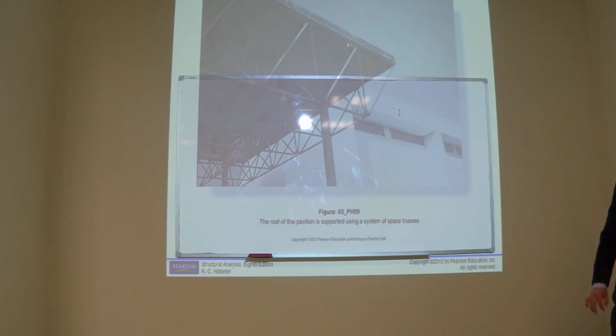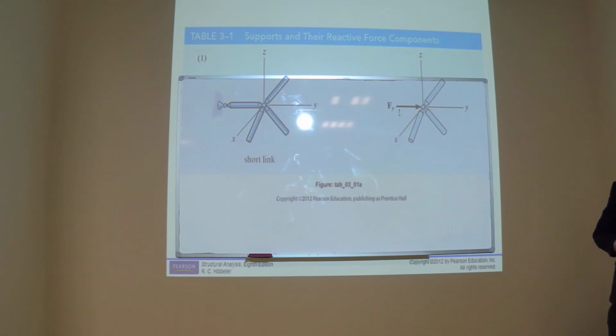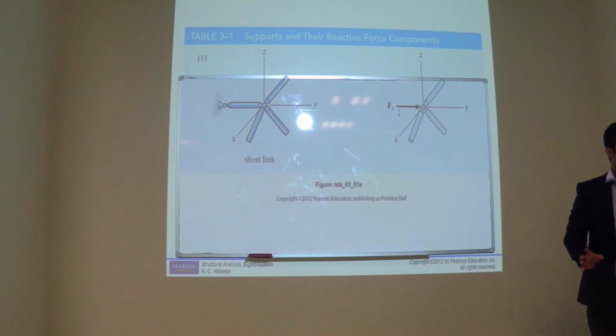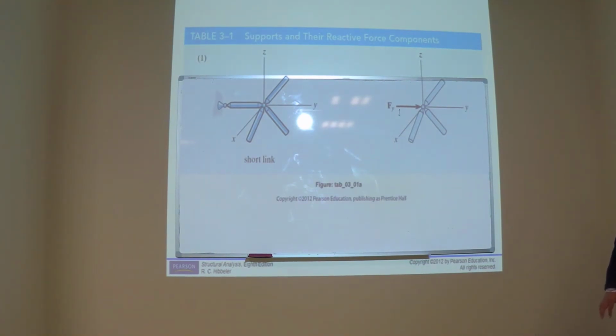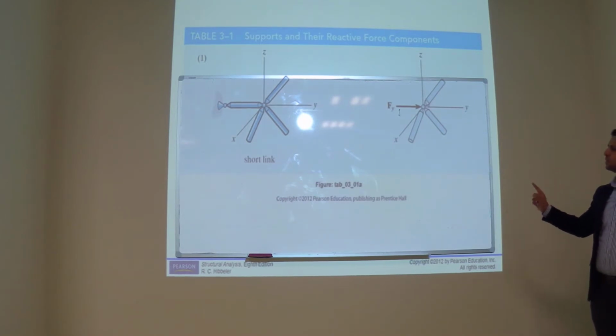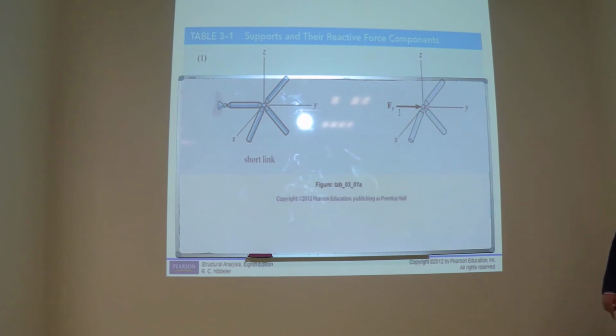If you see at these points, the load is transferred at the joints, and then from these points the load will go to the members this way, and maybe in the horizontal direction. Okay. So these are typical joints. I think you have seen these joints, and the support conditions are much more similar to two-dimensional trusses. It is a pin joint. All truss elements in case of a three-dimensional truss are pin joints, if you want to solve them by method of joints and the method of sections.